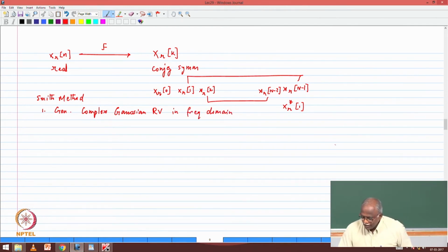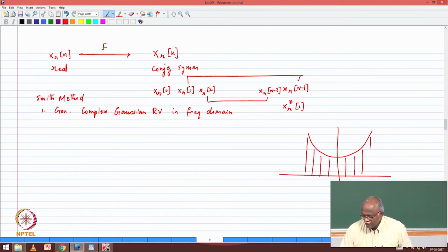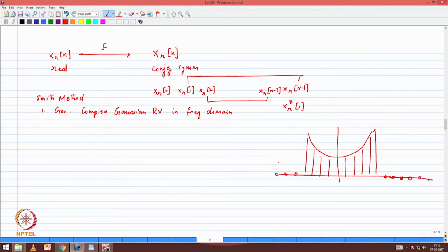What should you do for the filtering process? Very straightforward. Sample it. You get this as your sequence. Multiply by the FFT of it, and there are lots of zeros. Remember, there are lots of zeros present in the Fourier transform of your filter. So those zeros will multiply, they will remove out, and then take the inverse Fourier transform, and then get the XR, the output that we are interested in.